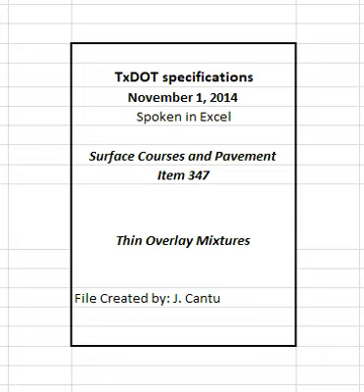The engineer may take production samples or cores from suspect areas of the project to determine recovered asphalt properties. Asphalt binders with an aging ratio greater than 3.5 do not meet the requirements for recovered asphalt properties and may be deemed defective when tested and evaluated by the construction division.